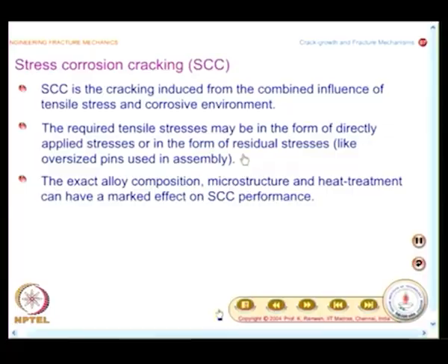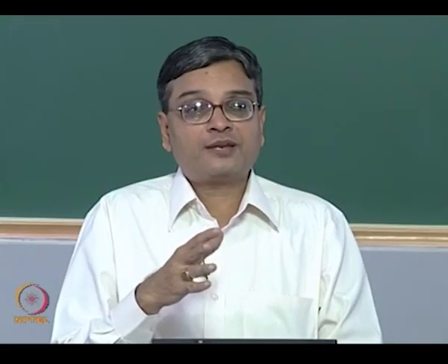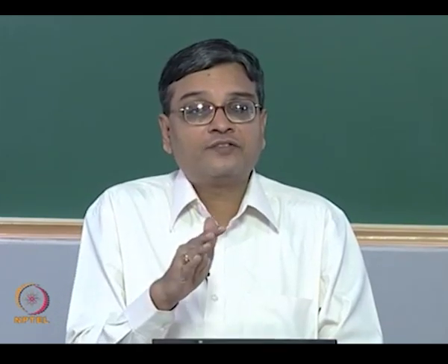See, if you go to a company, if they make a part by interference, they do not even recognize that interference fit would induce quite a lot of stresses in the vicinity. They ignore that when they do the analysis, they only take the external loads and eventually whatever component they have made, they fail in service.